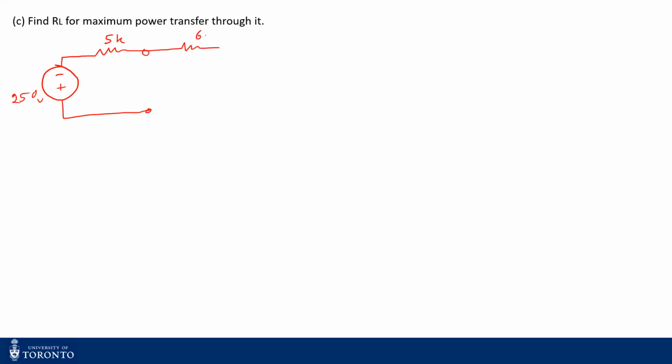Now I'll just connect the two circuits together. And I'll keep the RL, which was supposed to be in this position, right? I just keep it open. Now I have to find out the value of RL such that I have maximum transfer from both the left-hand circuit and the right-hand circuit, right? So basically I have to find another Thevenin across this RL, assuming that RL is open.